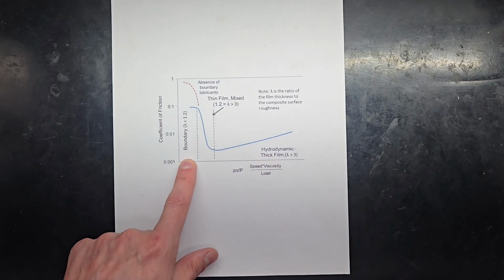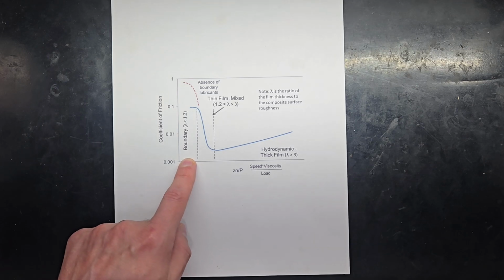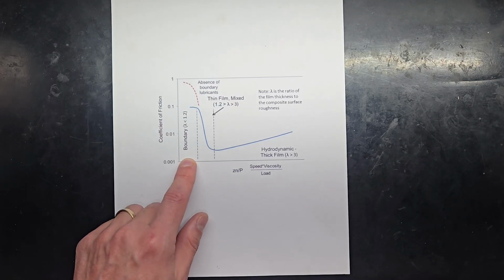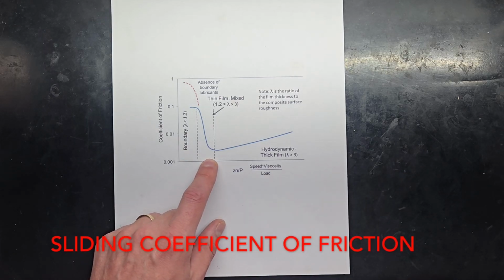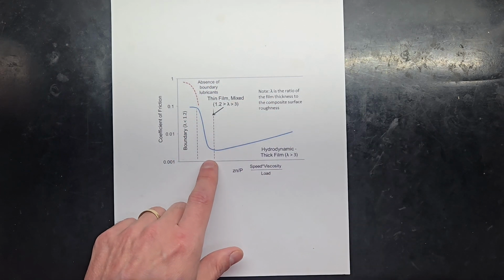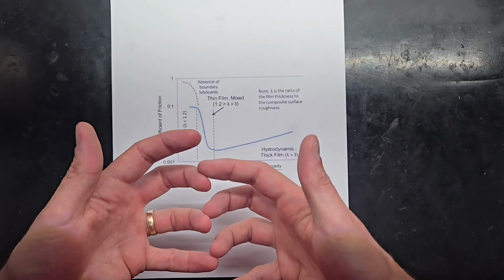Boundary lubrication, if we think back to the machinery or the Marks' handbook, is the lubricated friction. There is a layer of oil but for the most part, our bodies are in full contact with one another. As we move to mixed, now we're actually getting some of that body separation as we get some movement between the two. You're now riding on a little layer of oil, but you still have some asperities contacting one another. Asperities, the little peaks of both sides, are still going to be hitting each other a little bit.